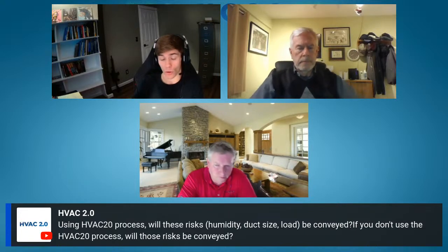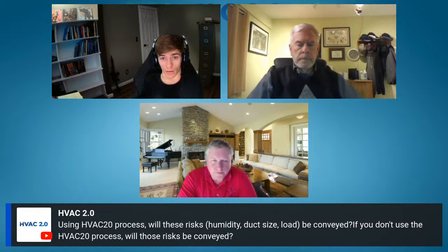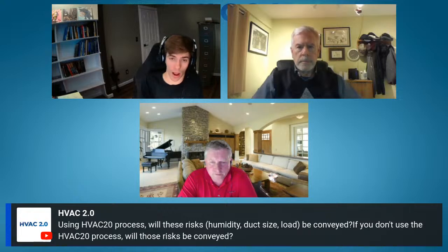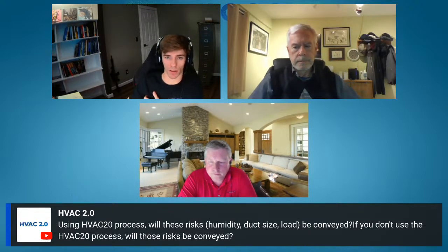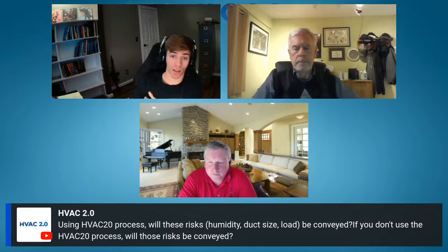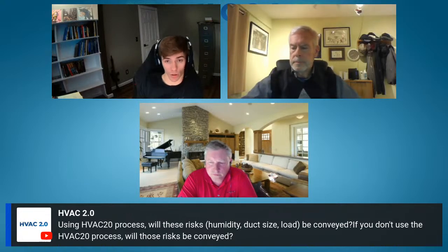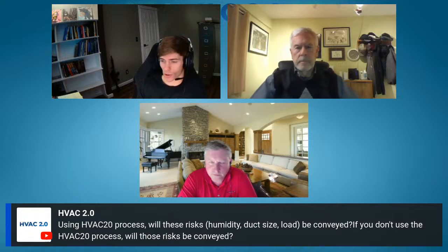You sized this equipment, and I'm also going to have this discussion before I even put the system in, but I'm going to give them those hygrometers after we get done, because I'm going to leave them knowing that it is their responsibility. The same way it's your responsibility to keep your oil changed in your car, it's going to be your responsibility to make sure that your humidity doesn't get above 50%. And if it does get above 50%, you can go buy about 5 to 10 portable dehumidifiers and start throwing them out, as many as you need to control it.